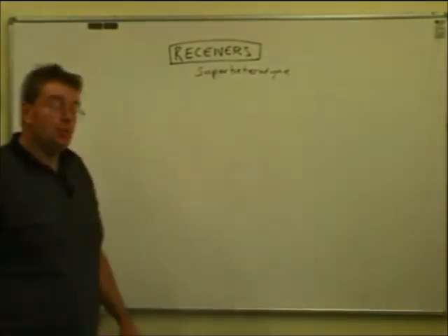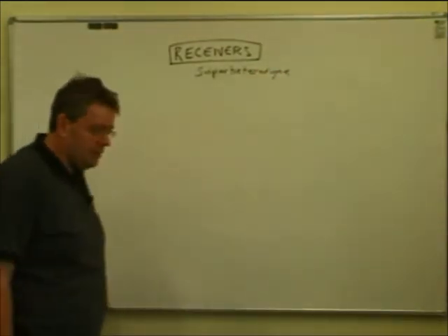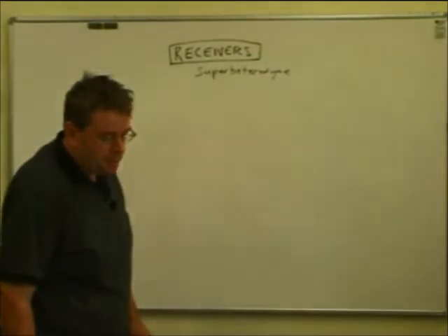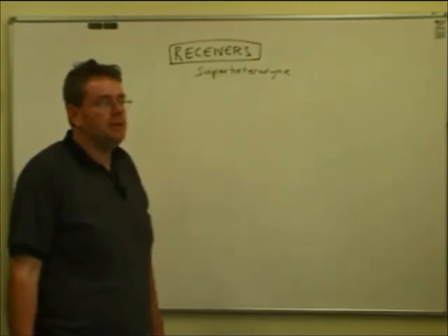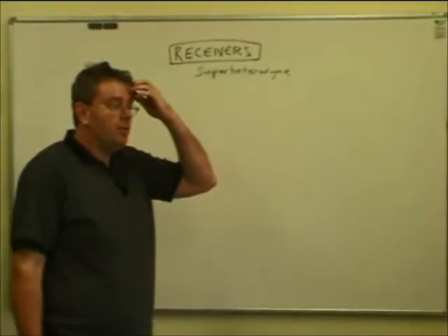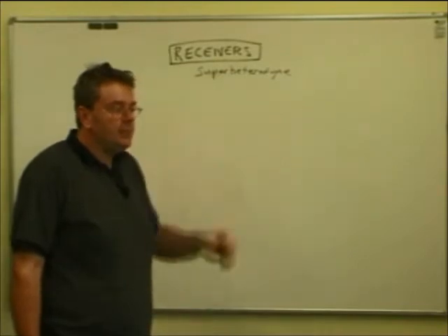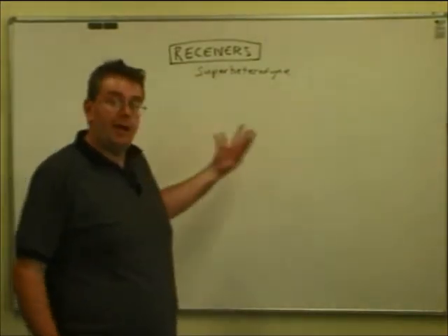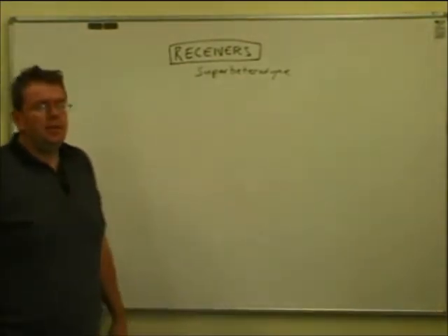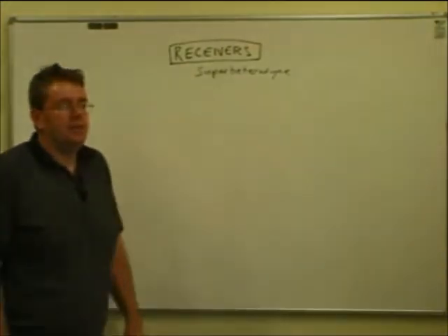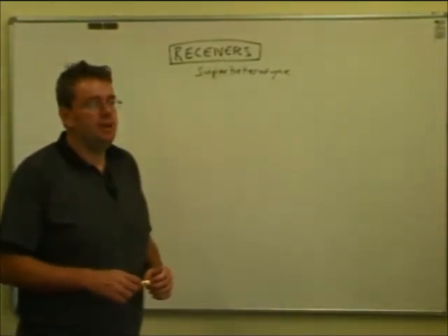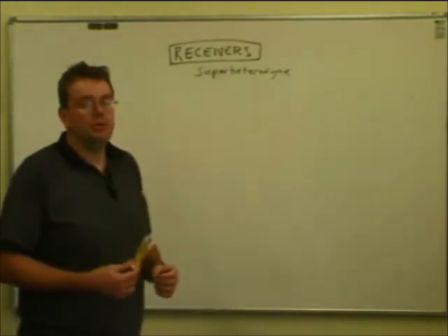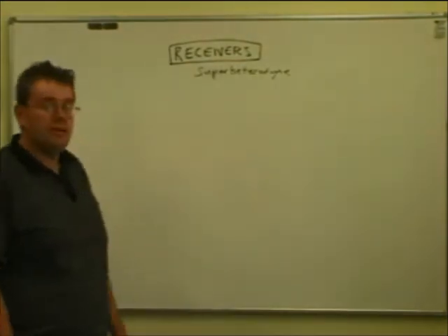The superheterodyne receiver got around a number of these problems, by making things quite a bit more complex, but it really got around the selectivity problem, and the stability too. Remember I said you could get feedback problems with that kind of layout. That's what we call stability, or one of the big factors that influence stability is the fact that the receiver will sit there and function nicely without misbehaving itself. The other factor to do with stability is whether or not it will stay tuned to the point we want it to, and we'll come on to that in a minute when we talk about local oscillators.